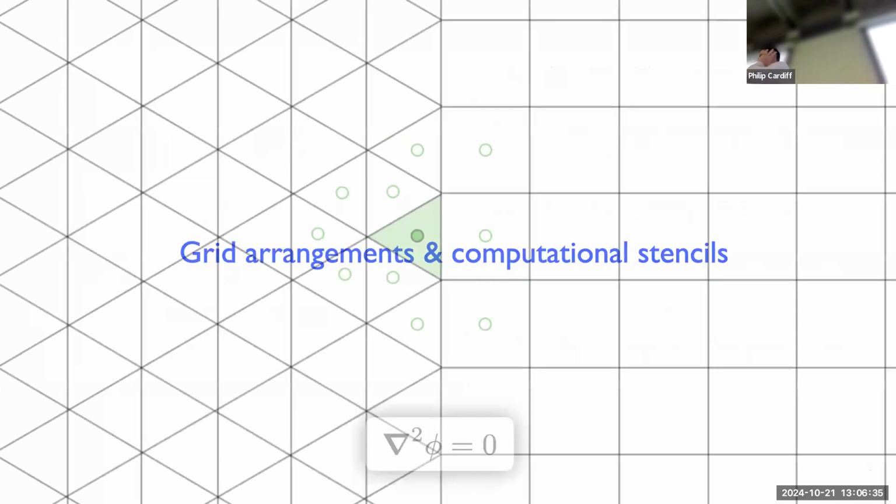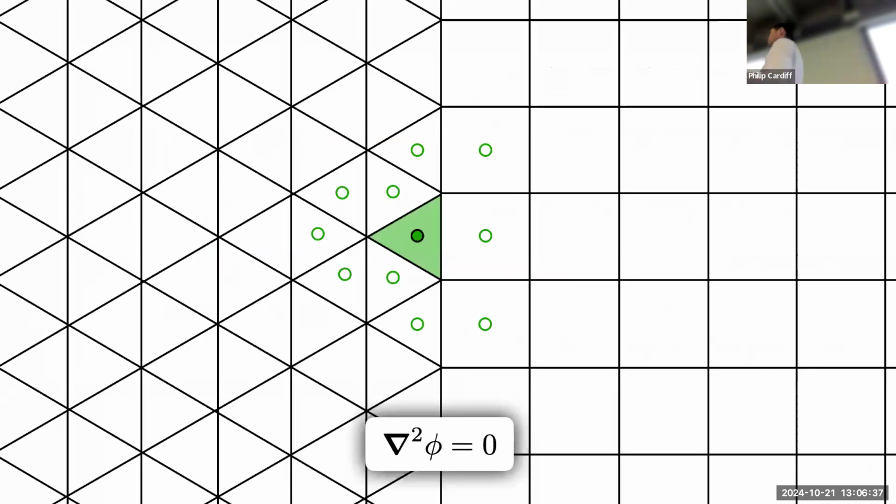Okay, so for the rest of the slides today, I'm going to just talk about some characteristics of finite volume methods and relative to finite element. And then I'm going to end by talking about how specifically they're applied to the Navier-Stokes equation. So when we're using Fluent, how exactly is Fluent doing this? So if we stick with this, our basic diffusion equation, what Fluent and OpenFOAM might use is what's called a cell-centered finite volume method. So for any cell, you can see it's a triangular cell here, and we have the unknowns at the centers of the cells. That's why it's called cell-centered.